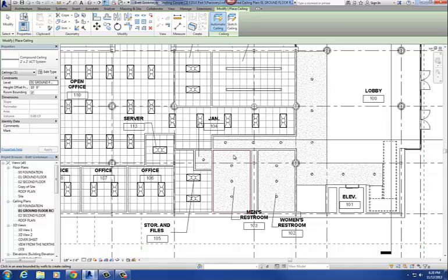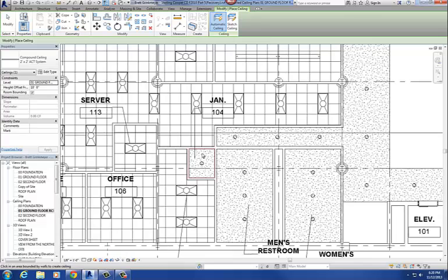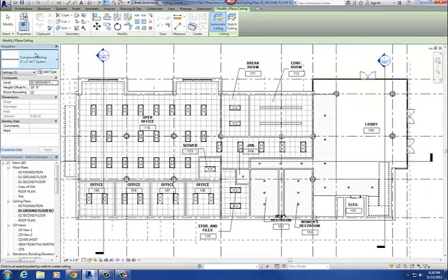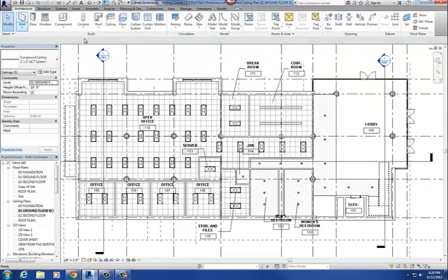It also keeps things from escaping that room. And we're using it in the small closet because it's such a small space that it's not worth putting in acoustic tile; you'd be cutting pretty much every tile. So small closets, nice finishes in ceilings, and bathrooms are usually where you'll find gypsum wallboard ceilings.